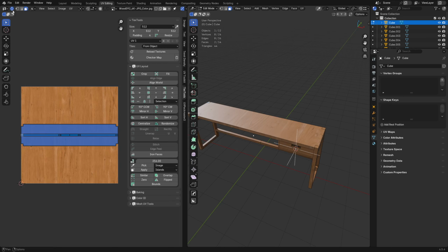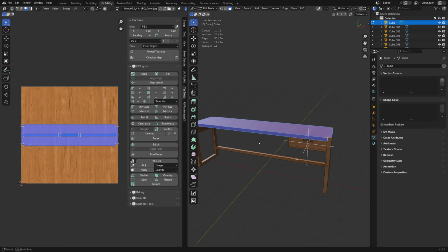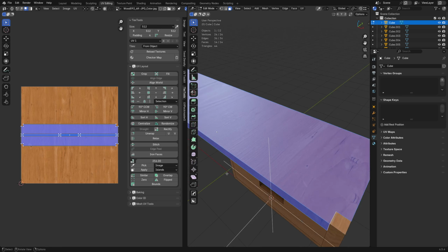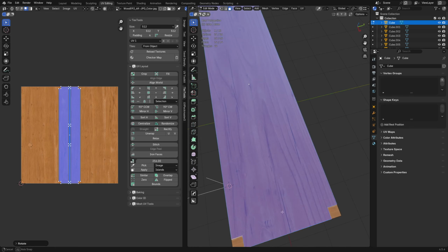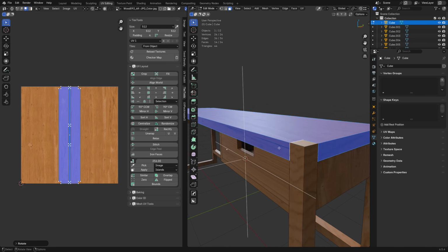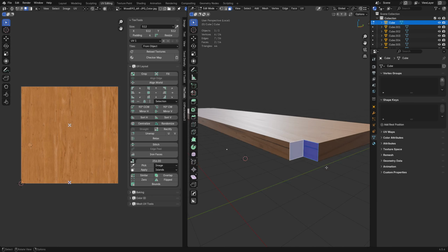All right. But I'm not going to use that for this. I'm going to have to select everything with A over here to make sure that my UVs show up in 4.5 LTS, right? And now that's in the wrong direction, so we just press R and we can rotate and hold Control. That's going to get us in the right direction. These are the long strips here, obviously, so these are going to also look correct. We do have those little short squares in here. They're not super important because we can't even see them.